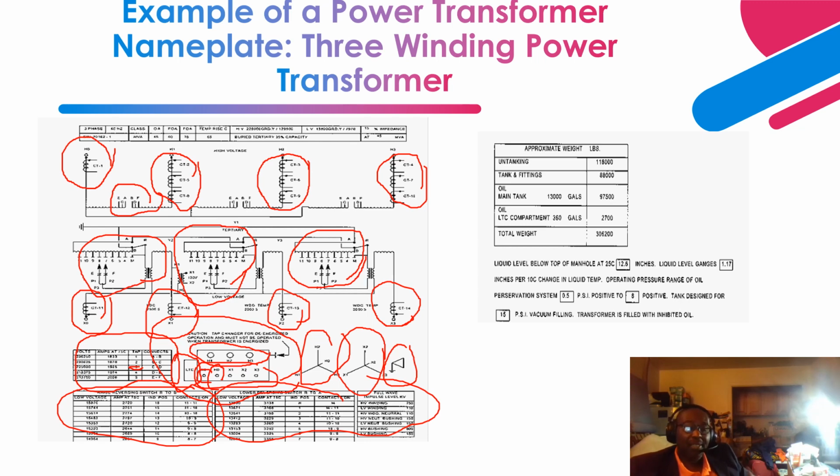Remember, I may mention that the corner of the delta winding is grounded. The goal is to basically mitigate overvoltages that can occur due to stray capacitance from the insulation. If that is not done, it is basically going to burn the insulation. The insulation is going to fail due to overvoltage condition. So we corner ground the delta winding, and that corner ground is brought out of the tank on top of the tank. So you see a typical bushing for this tertiary winding.